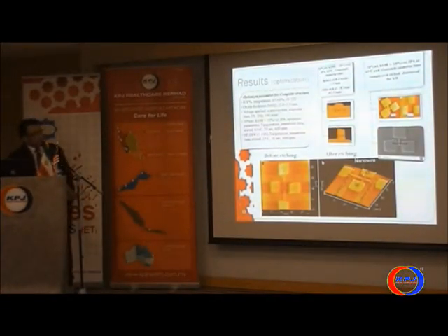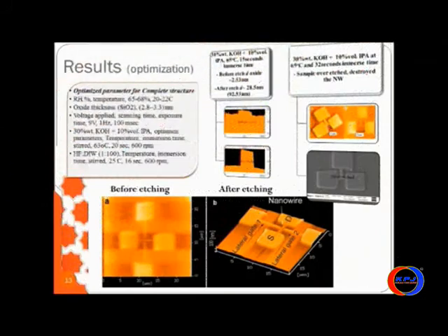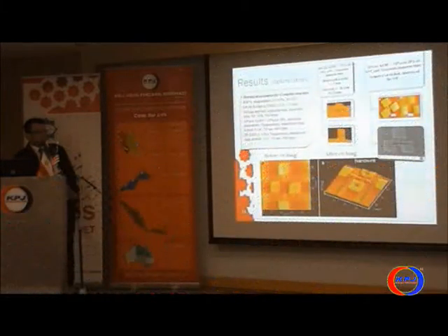So here the overall optimization can be seen. Here, this is the mask. AFM makes this mask, and after the removal of the mask and the removal of the silicon, we got the structure. This is the source, this is the drain. Current goes from source to drain, and the gate from 2 sides is going to control it.